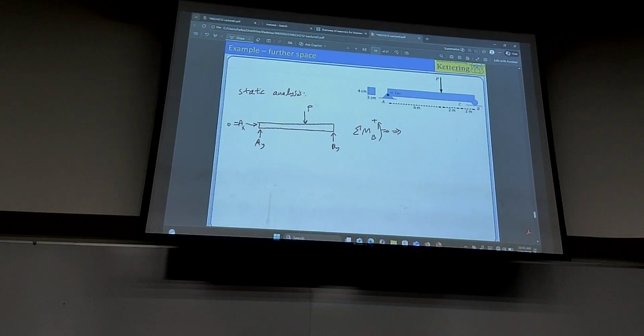So again, let's do a review. This basically means, in math or statics, summation: scan through your free body diagram, take moment of every load about point B, and combine them to 0. If it's counterclockwise, set it to positive, otherwise negative.